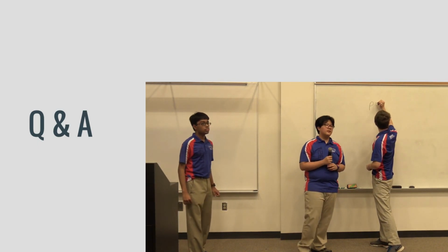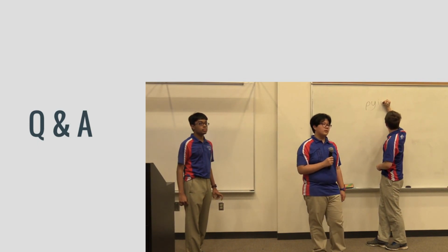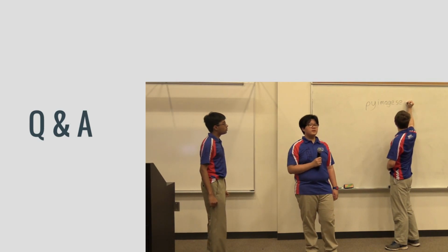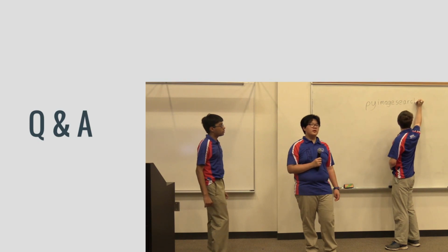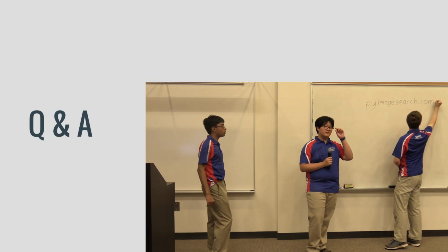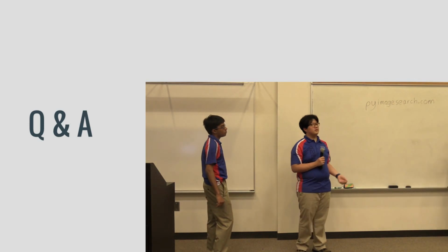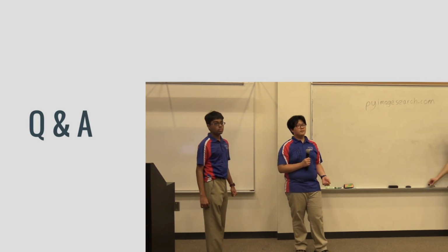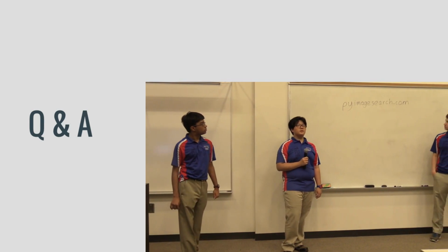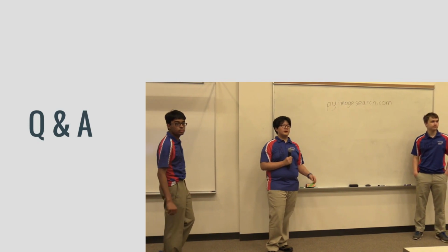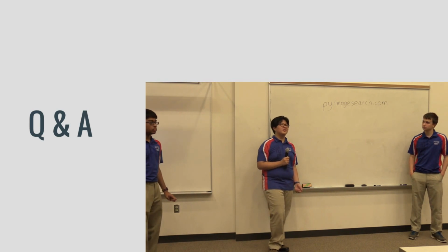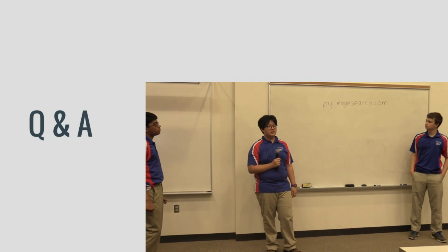Any other question? Did you find yourself spending a lot of time optimizing your software to make it work better? Yeah, a little. When we're actually doing the OpenCV stuff, we're using the Raspberry Pi 2, and it isn't a very great computation platform. So we actually had to downgrade our image resolution quite a lot, more than we would like. But there are a lot of ways to speed the program up. You can blur your images and set different types of filters on it, so you have blockier pixels, which makes image processing a bit faster.